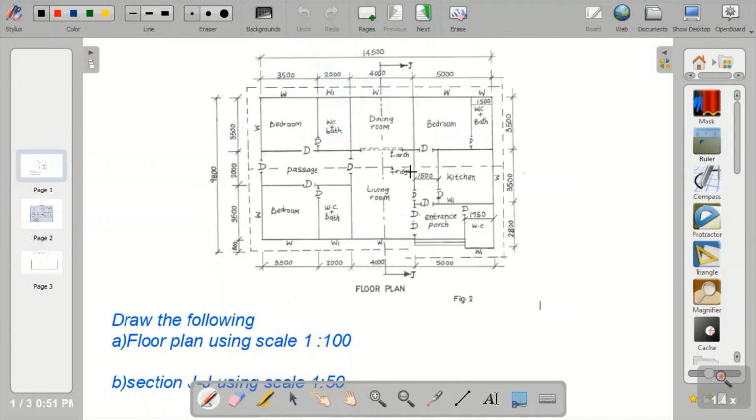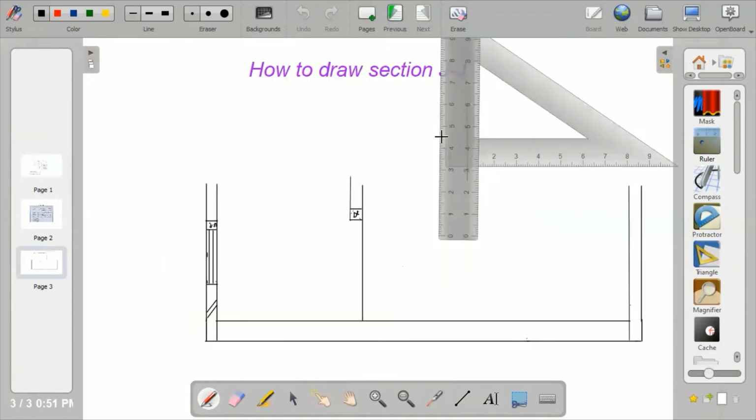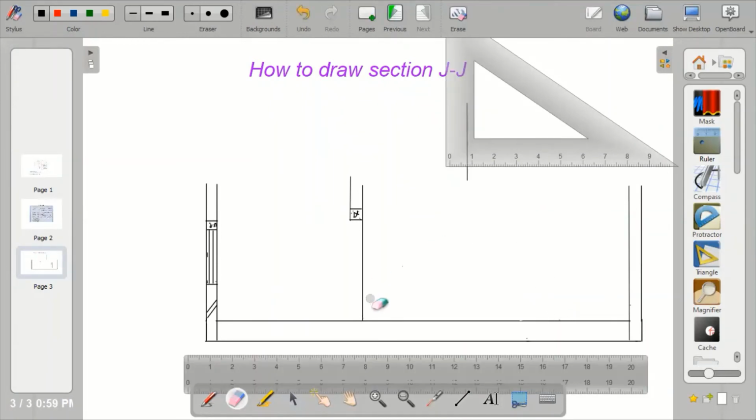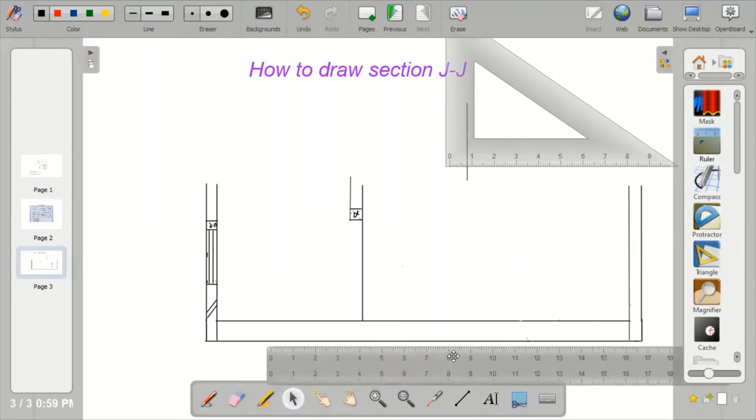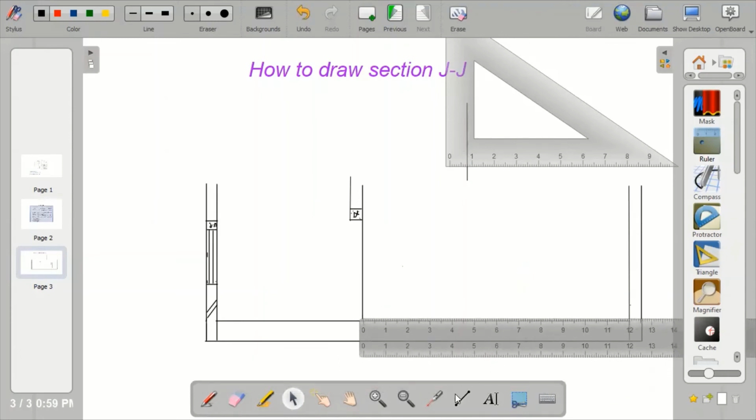Now, when you look towards your right hand side, after the beam, you will see a single leaf door. After the single leaf door, you see another double door. So before we position the single leaf door, we'll check the measurement again, which is 3,500 from the arc. So I'll go back to my drawing, bring out my ruler, and measure from the arc. Okay, so I'm going to place the first door within 7,000. So this is my 7,000. So at this point, I'll draw my first door, which is a single door.